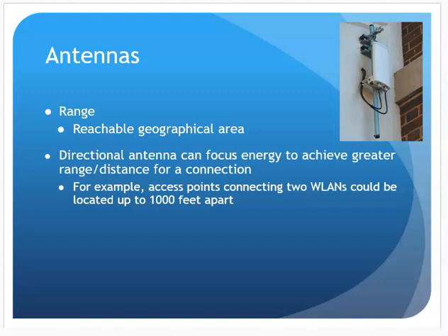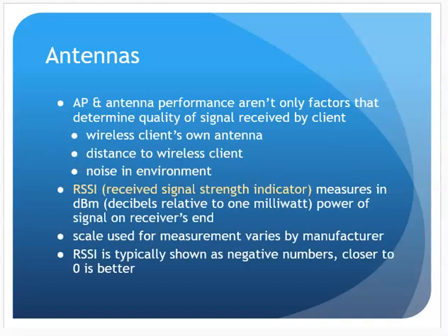So when I'm dealing with antennas, I think about range. What kind of geographical area can I get with a particular antenna? And directional can extend that range, and I might see these kinds of things giving me that directional antenna to go from a building out to maybe a booth in the middle of the parking lot for the gas pumps. You might have a directional antenna connecting those two together. Just giving you an idea where you might see that kind of thing.